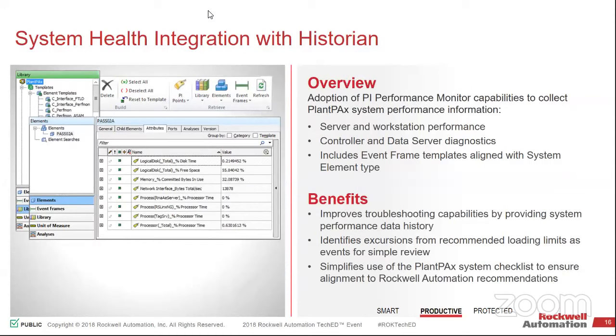I can now see them in a nested view, and they have parents. So any changes that you make to the top end side propagate to all of the children inside of it, meaning your scan times, the parameters that you would set. It makes it a lot easier to be able to do bulk configuration changes. So all of that is now part of it.